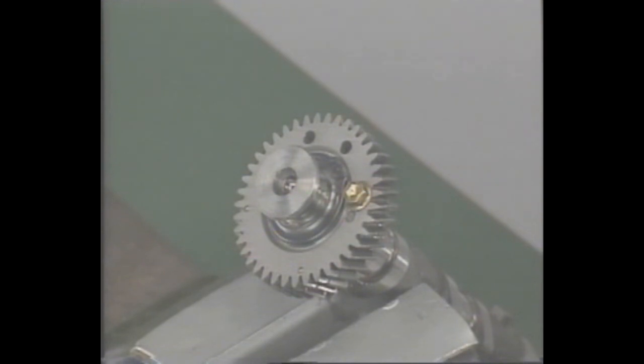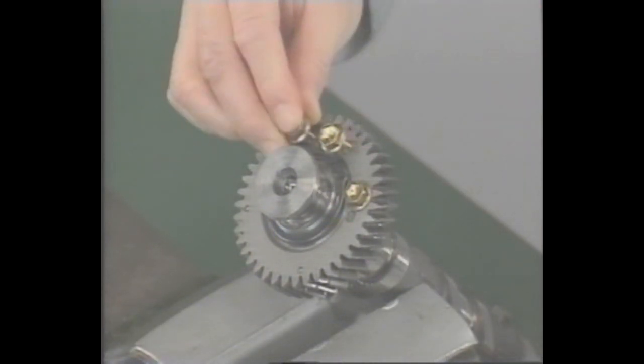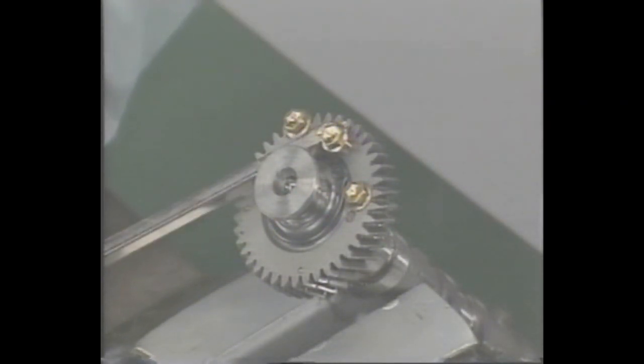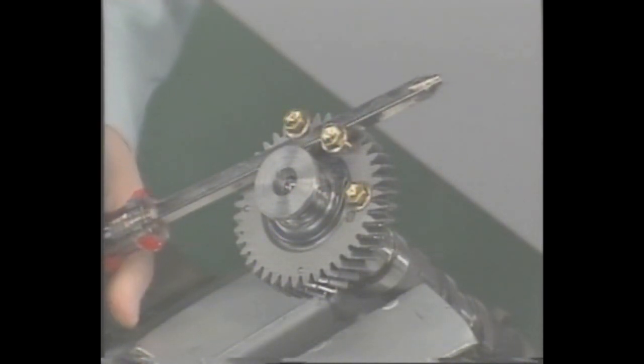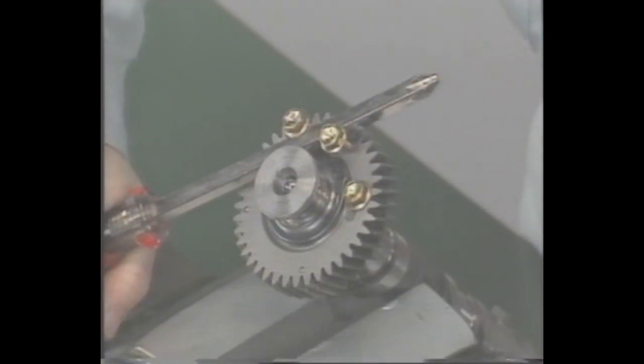To remove the subgear from the intake camshaft, mount the hexagonal wrench head portion of the camshaft in a vise using a protector made of aluminum or the like. Insert 2 bolts in the service holes of the camshaft subgear as shown. Inserting a screwdriver between the 2 bolts, remove the service bolt while removing the camshaft.